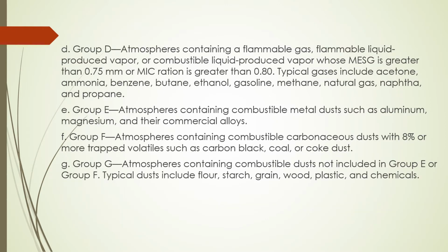Group D, atmosphere containing a flammable gas, flammable liquid produced vapor or combustible liquid produced vapor whose MESG is greater than 0.75 mm or MIC ratio is greater than 0.8. Typical gases include acetone, ammonia, benzene, butane, ethanol, gasoline, methane, natural gas, naphtha and propane.